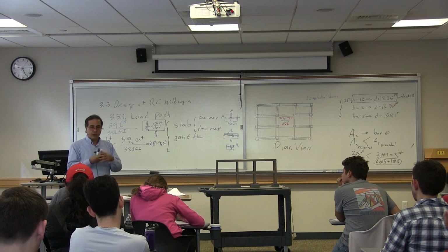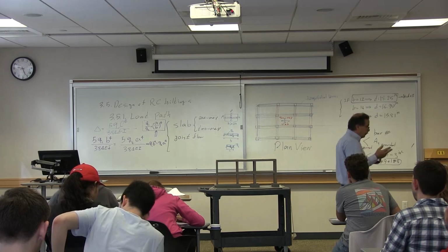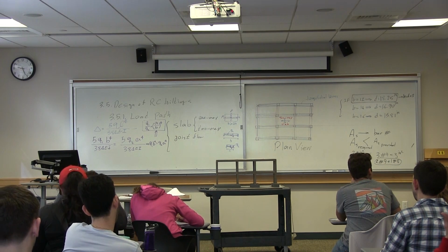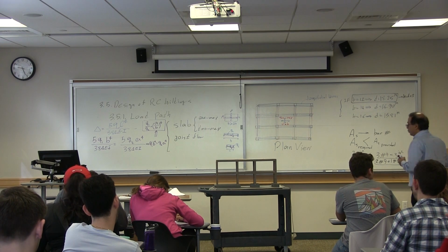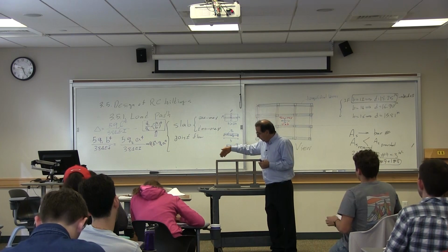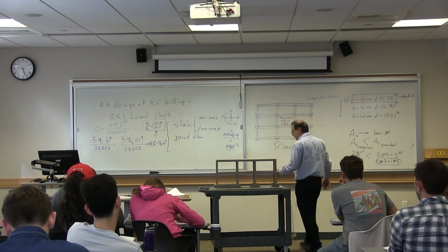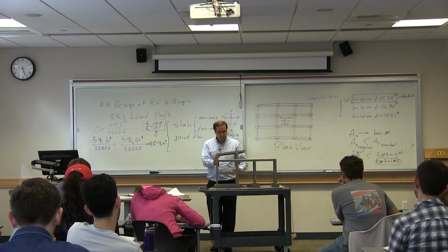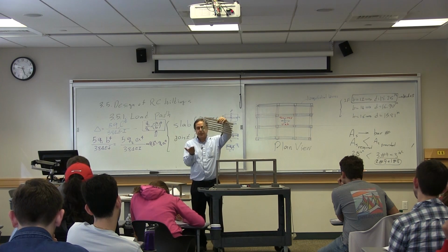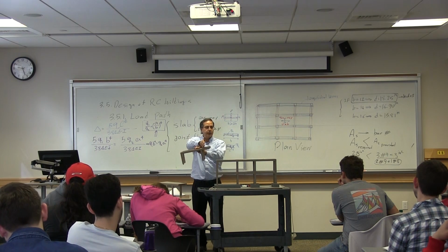Does that make sense? So the first thing you want to do is you decide what type of floor system do I want to choose. Because of 2 reasons. Reason number 1 is the load path. For instance, if I choose the joist floor system in the longer direction, which usually we do in this case, the load goes to this beam and to this beam.